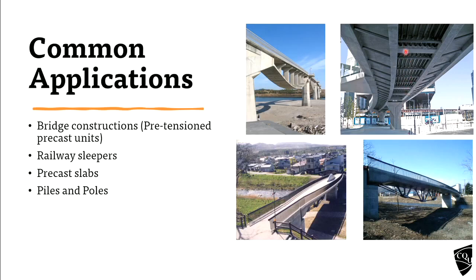So all these steel tendons are coated with the epoxy. Because if you let the steel be exposed to the environment, it will easily corrode, so that will make some problems. So these ones, it's still exposed to the environment. You can see the steel, but all are epoxy coated. So no direct contact with the environment for the steel. So that has the longest lifetime, less maintenance.